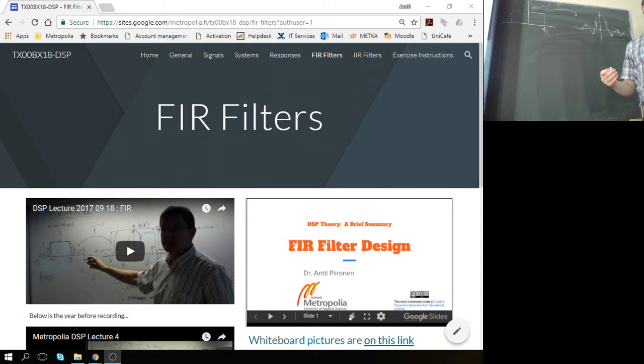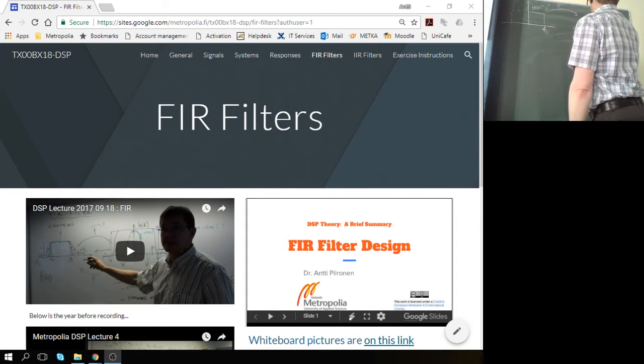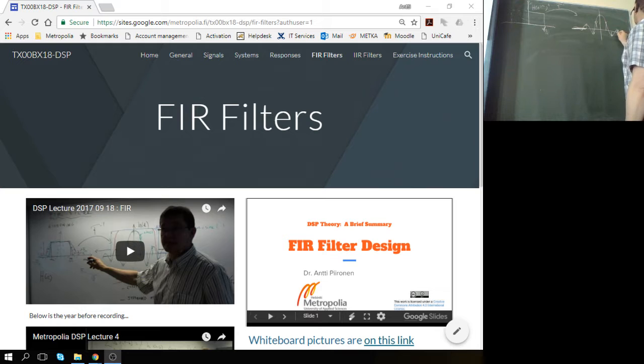And how to make it a finite impulse response? Well, you cut it there, for example. So set the value to 0 after those points, meaning mathematically that you are multiplying this sinc function with a box. So there's a window w(n), and there's also that sinc type function.